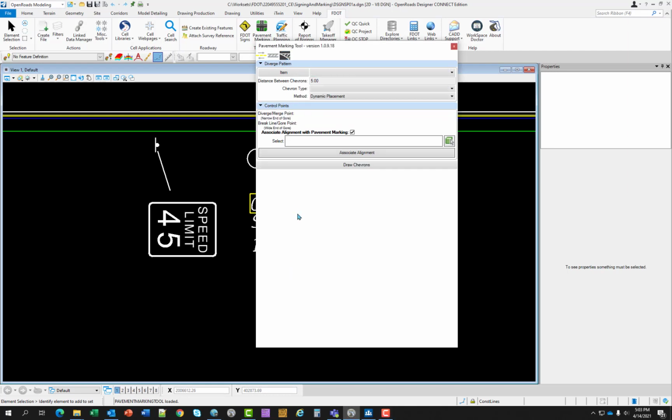The final mode, the chevron diverge merge mode, is used for traffic channelization at a gore when traffic flows in the same direction as seen in the figure below, which is in the training manual. Please refer to design standards for specific design criteria.